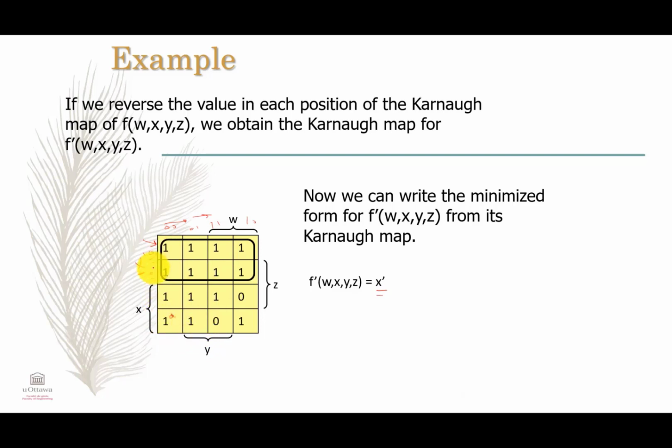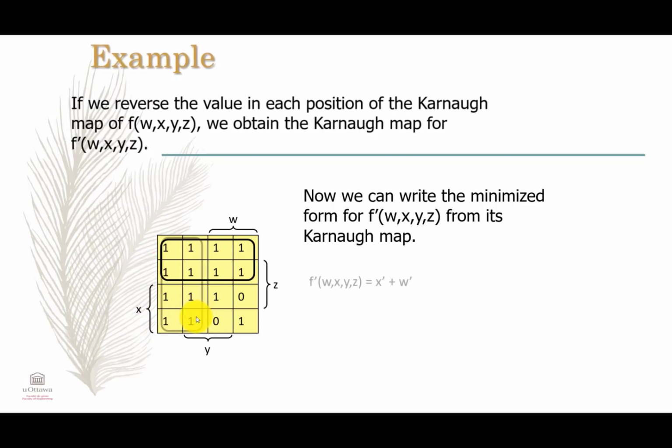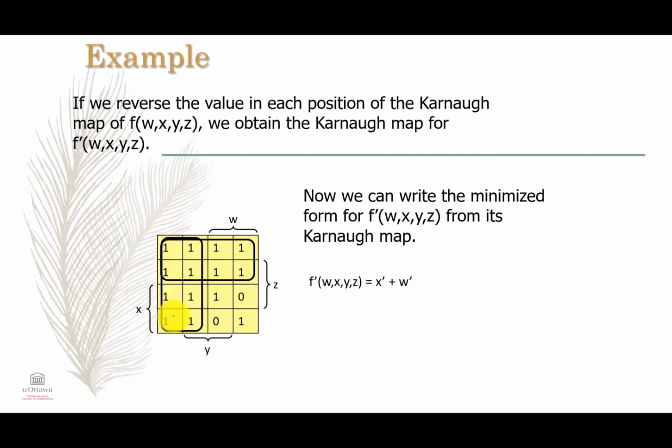This one can be grouped in a group of 8. That's why I choose to group it. And when I group these, look here, because you're going through all the rows, you should exclude them. Now, what is not changing here? Remember that is 0, 0, and 0, 1. So what's not changing here? It's simply, guys, w prime. That's why we wrote w prime. Now, can we group the remaining ones in a group of 8? Unfortunately, we cannot.